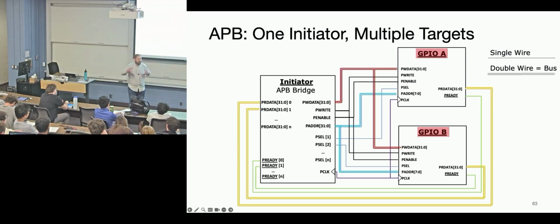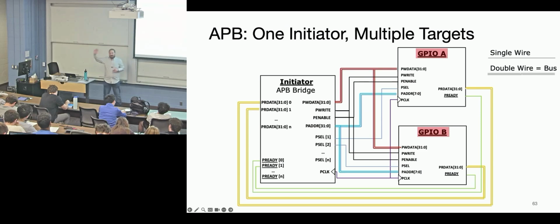Asynchronous clock. Yeah, so if you have 2 clock domains, they're not synchronized. Because if your data transition is always guaranteed to be away from your clock edge, it never happens. You never have to worry about this. But if you have some asynchronous device over here, like a windmill or something, that's going to throw in edges whenever it wants to, then there's a probability that something bad could happen.